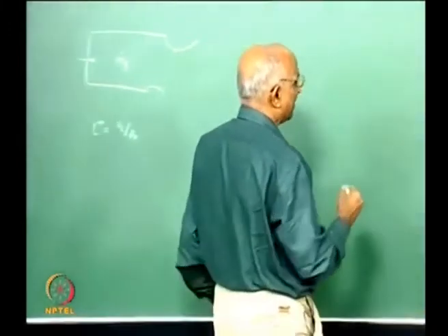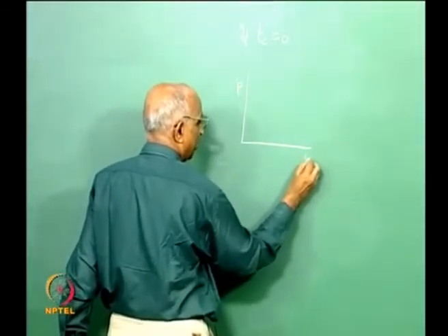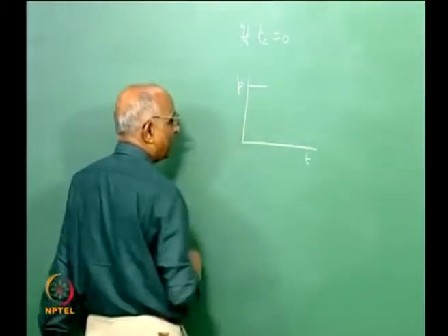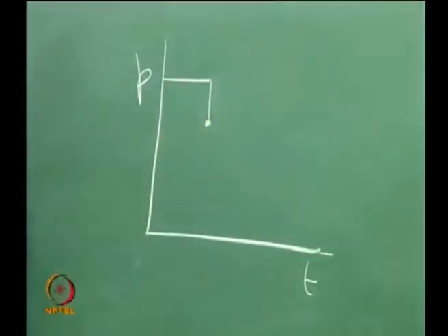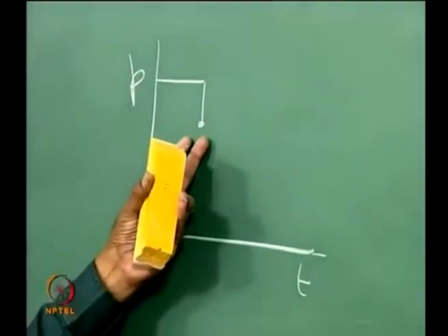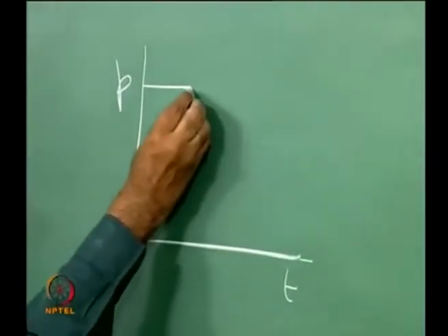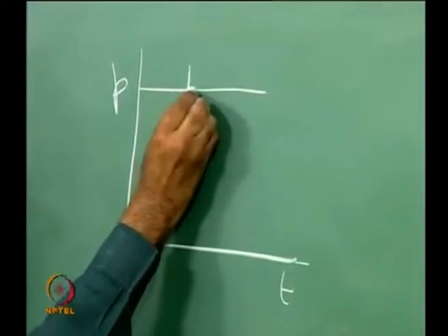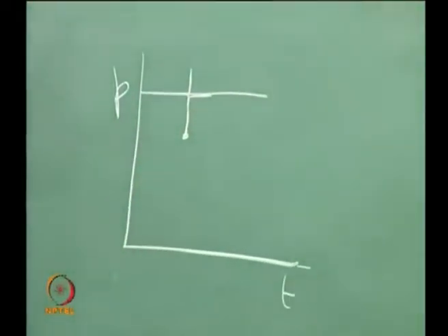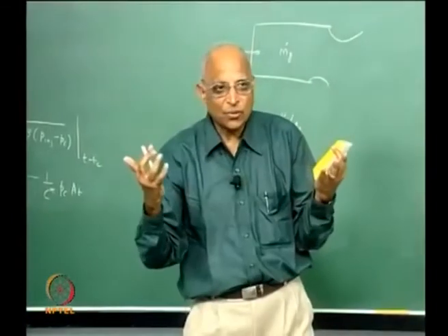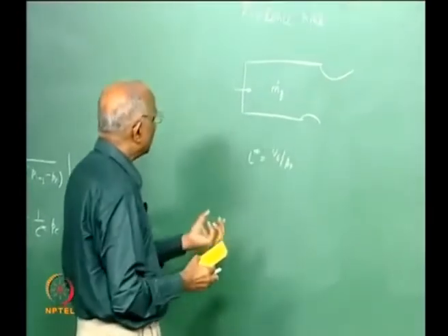Let's try to imagine this again. Let me say my chamber pressure with respect to time, originally I had 5 bar, it drops to 4.5 bar, but there is no time delay, immediately it burns and immediately it goes out. What is going to happen? It goes back here and adjusts, goes back here, adjusts. Therefore, without a time delay, I cannot think in terms of these oscillations. And what is the role of this time delay? Well, there is a lag and that is what causes it.